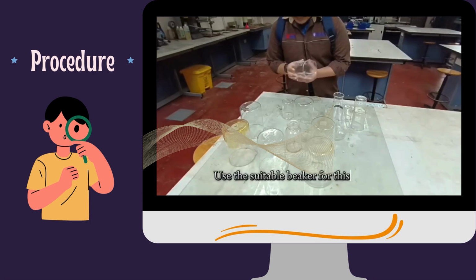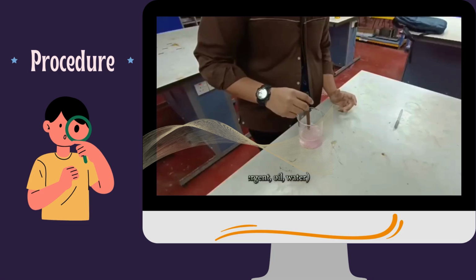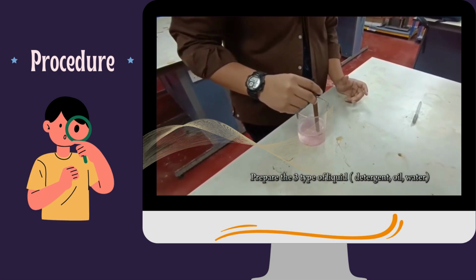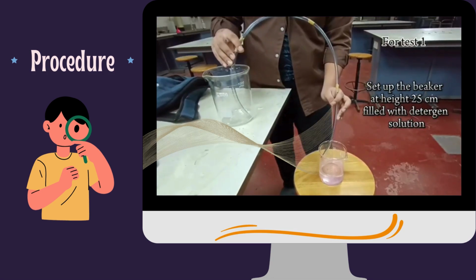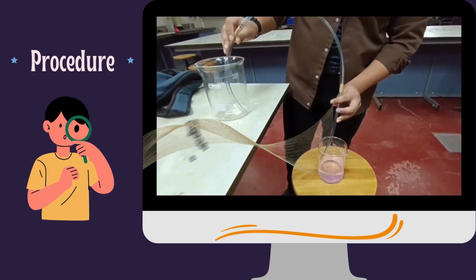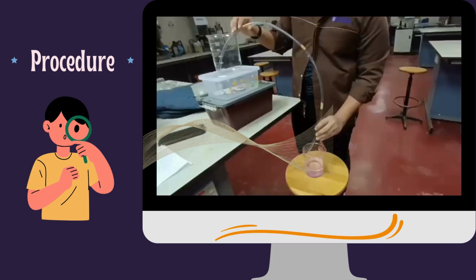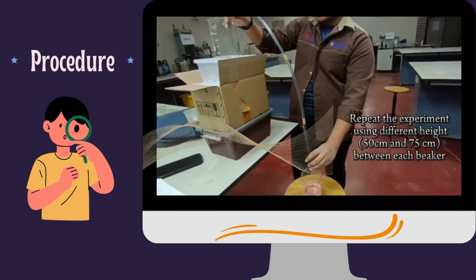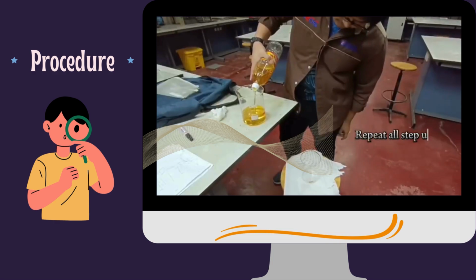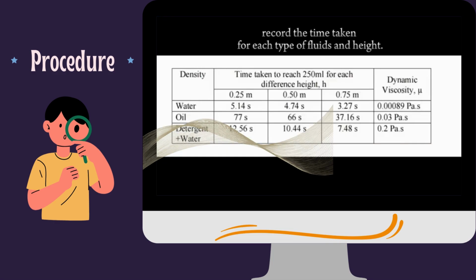Use a suitable beaker for this experiment. Prepare the three types of fluid, which are detergent, oil and water. For test 1, set up the beaker at height 25 cm and fill with the detergent solution. Flow the fluid from the beaker using the tube and start the stopwatch. Repeat the experiment using different heights, 50 cm and 75 cm, from the beaker. Repeat all steps using different fluids, oil and water. Record the time taken for each type of fluid and height.